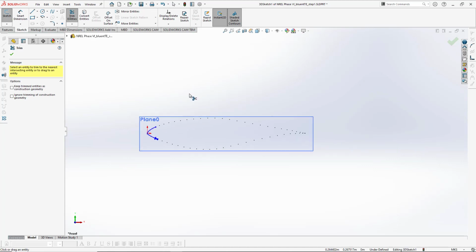We basically want to divide this wind turbine blade into three sections: leading edge, upper section and lower section. I will further divide the leading edge into two parts, the upper side and lower side, but that will be done in ICEM CFD, not in SOLIDWORKS or SpaceClaim.